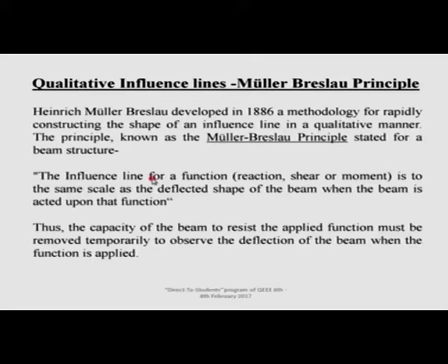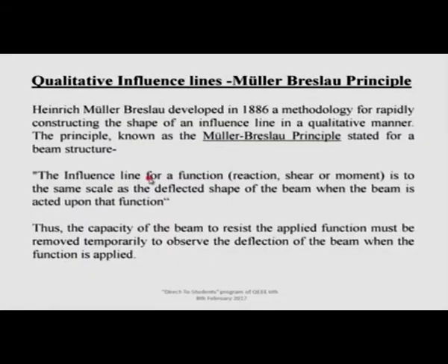So, how does the beam look? It will be trying to fall down from that end. Now, while it is falling down at that end, let me prop it with the same reaction I have removed and see what shape it takes. That is the influence line diagram for the reaction itself. It looks ridiculous, what is the relationship between them? So, that is the Muller-Breslau principle.